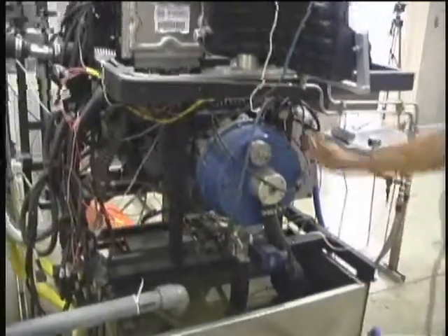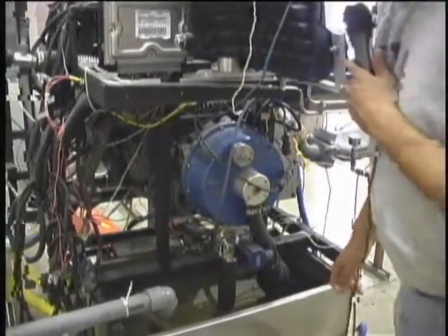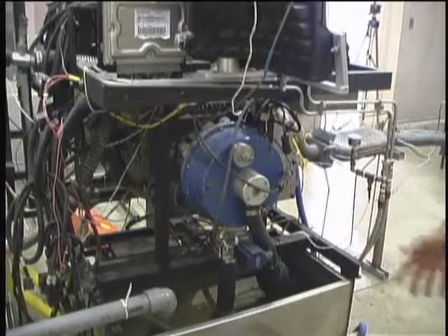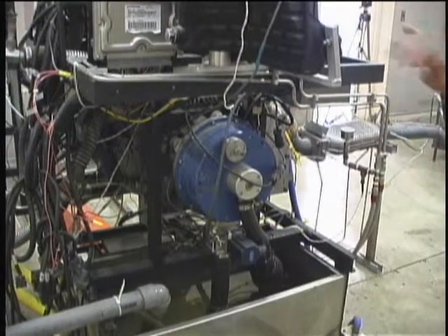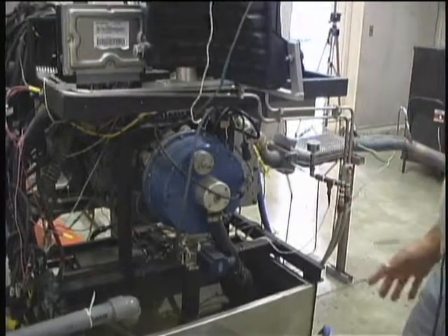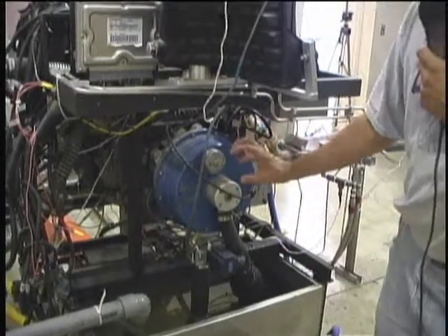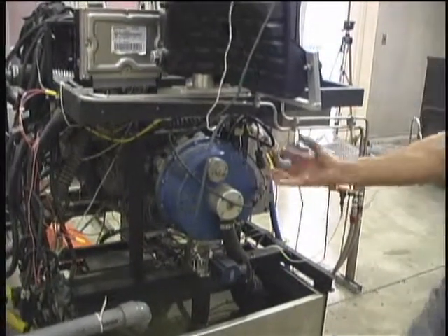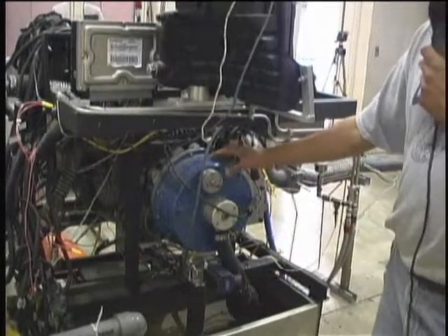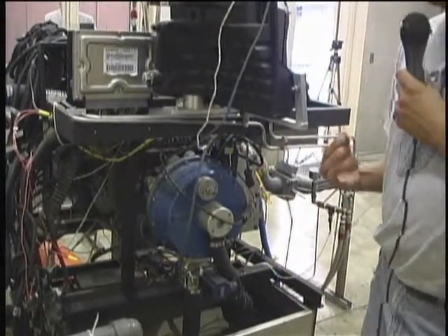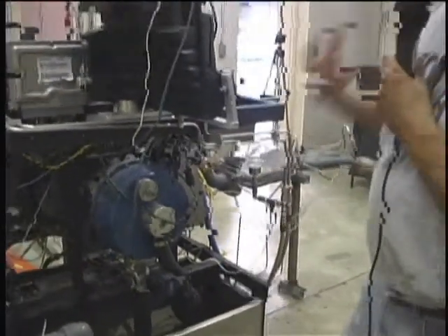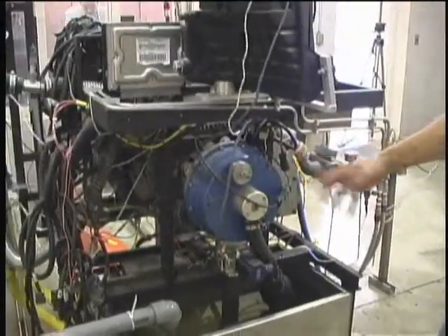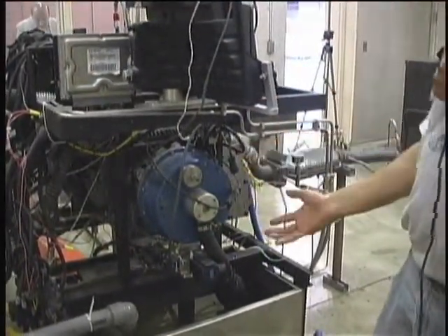Next is your load absorber. The load absorber is a Superflow load absorber, and basically it applies artificial load to the engine. It has two impellers. One impeller is hooked up to the engine's RPM, so it's spinning at the revolutions, 5,000, 4,000 RPM, and you have another impeller that doesn't move. It's just stationary there. When you start applying fluid pressure to the one that's not spinning, that one wants to rotate. That one is hooked up to a strain gauge, and that converts it to horsepower and torque. That's how you get your measurement.